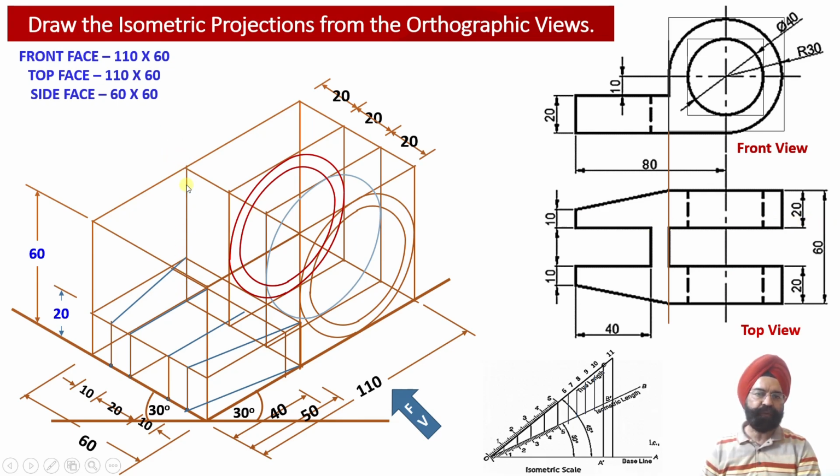and corresponding to this fourth surface, as we have discussed, because it is lying toward the rear side of the solid, we are going to obtain only the outer circular web over here. And once again, the total circular web will not be visible. So this portion will not be visible to the observer because it will be covered by this thickness of the web over here. So this way, corresponding to surface 1, surface 2, surface 3 and surface 4, we have been able to obtain different circular projections into the isometric projection over here.